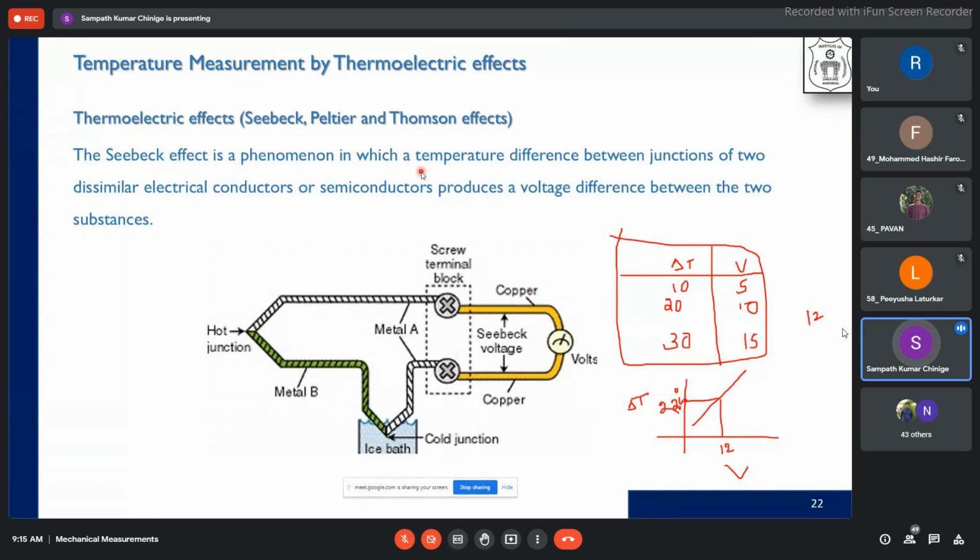So the main thing that we look out for here is a high input impedance measuring instrument to measure the voltage that is created in the particular circuit. We don't want errors because of current passage. Voltage variations actually create error in the final measurement, so we don't want that to happen. Therefore, we always try to have as low current passage through the circuit as possible. That is what the Peltier and Thomson effects are, and in a thermocouple circuit, we try to eliminate these two effects.